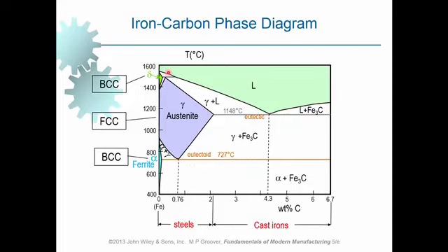And this is, of course, liquidus, and this is solidus, this one. Any material below this solidus line will be solid. So what is meant is that material that is above this point and below this point, this is all solid. However, different types of solid material, which is not the case for eutectic. For eutectic, above this point we will have liquid, below this point we will have solid. For eutectoid, above and below both solid.